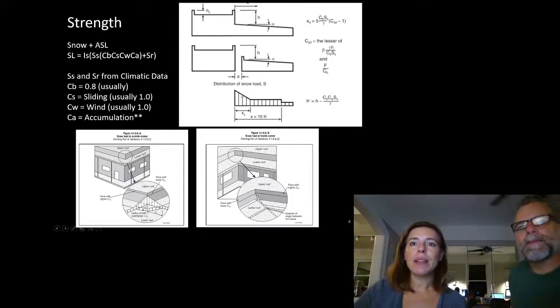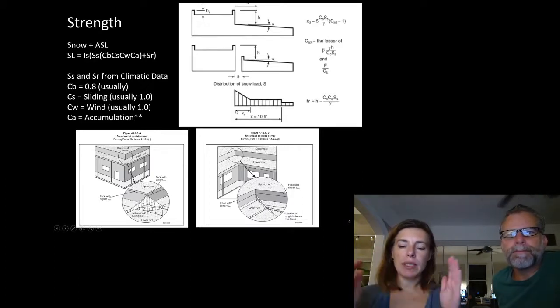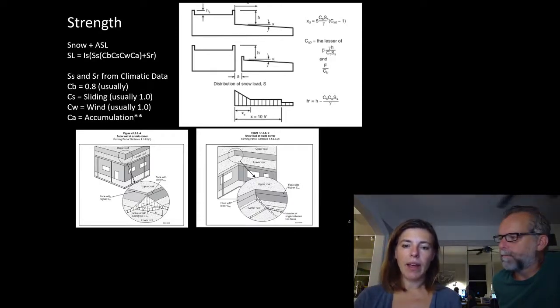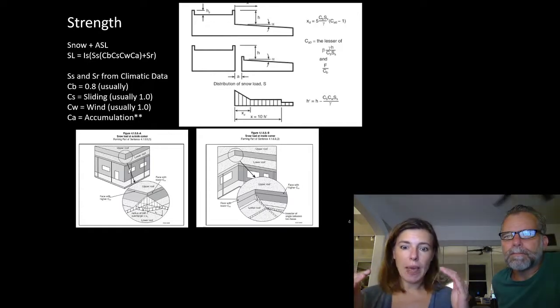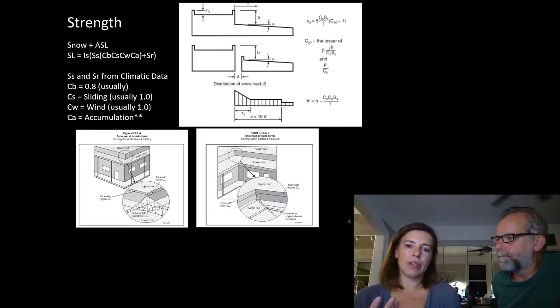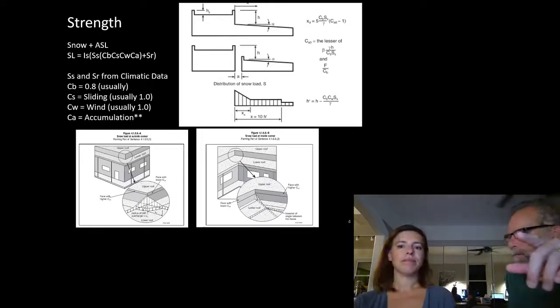If I'm in a relatively tight zone right here, I might just use the maximum snow load and see what the design implications are. Because it's certainly not going to hurt if we're talking 3.5 kPa, and instead of going 3.5 to 3.3 kPa, I'm just using the 3.5 kPa over the whole surface. We're talking about a very nominal structural increase, and it's conservative.